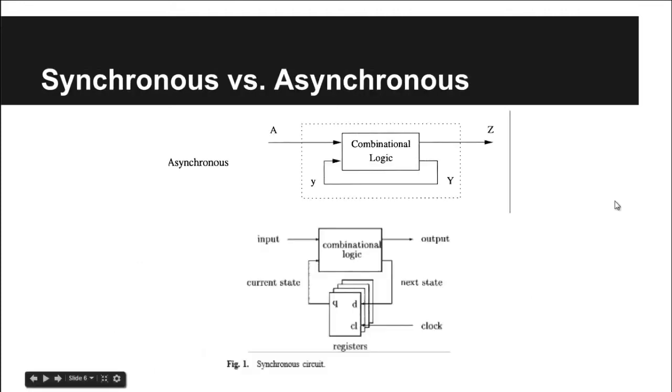As a basic comparison, we have this diagram where we see some arbitrary combinatorial logic hooked up in both an asynchronous and synchronous manner. For the synchronous logic to work properly, the states are stored in some register, and they wait for the clock pulse to send it off as the current state for the combinatorial logic. However, in the asynchronous setup above, the clock and register are bypassed by sending the next state output directly into the current state input, and the next step of combinatorial logic begins immediately as this change in input occurs.